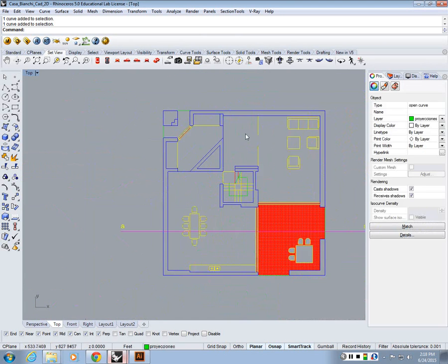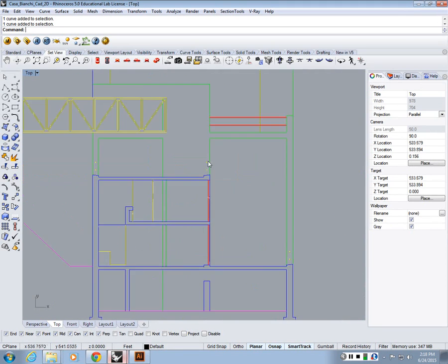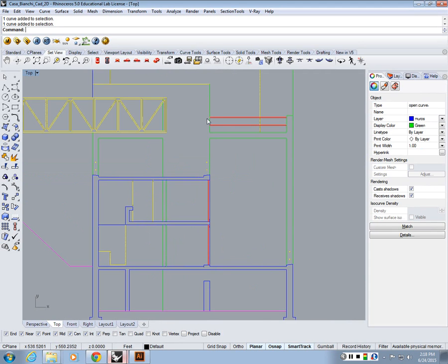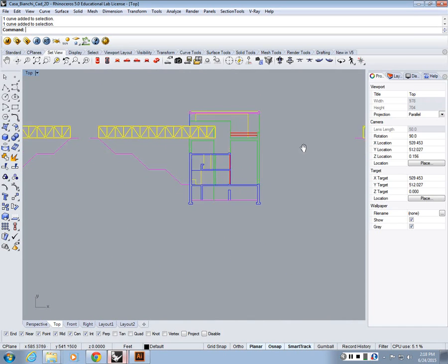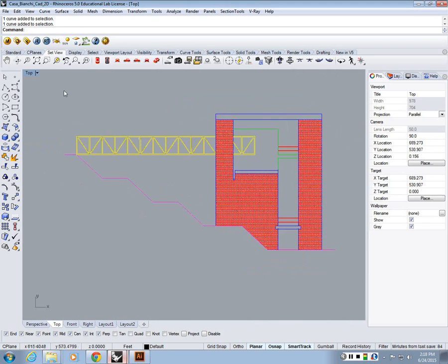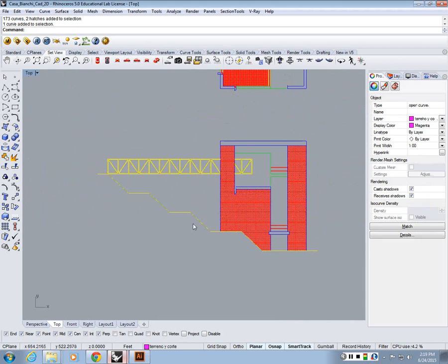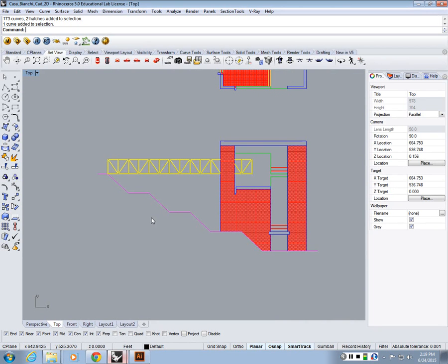So these elements, like furniture, stairs, the ones that are behind our view, further back in elevation, they're on a different layer, so they will be lighter when we apply them in elevation. Okay? And when we do elevation drawings, the principle is similar. The closer elements to our view will be darker, and the ones behind will be lighter. Okay? And the ground line will be thicker because we are cutting through the ground. That's like a thick element.